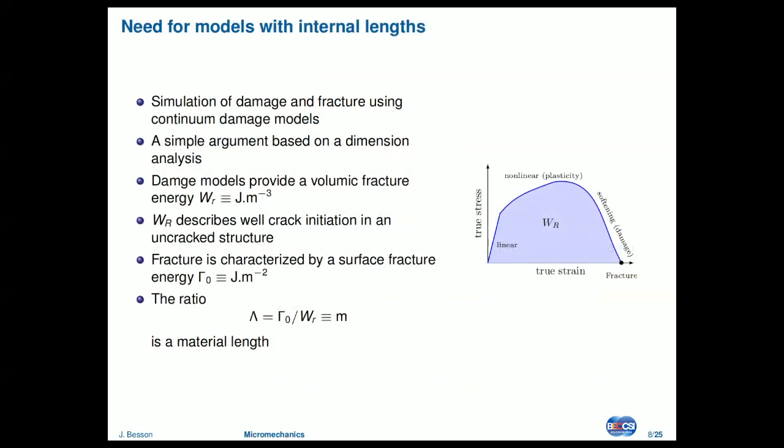And I want to outline that when you have a damage model, then you need to introduce some internal length. We're using continuum damage model. In the first session, in the first evening, we spoke about engineering damage mechanics. You can see this presentation as an attempt to do engineering fracture mechanics. So we need a model with softening. That's what you have here. What I plot here is the true strain on the true stress. So you have elastic behavior hardening and then softening up to failure here.